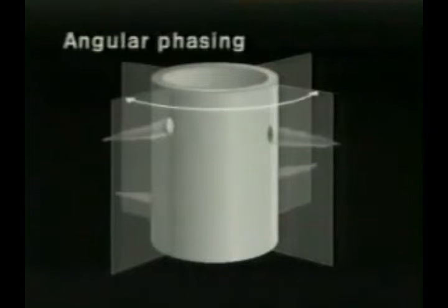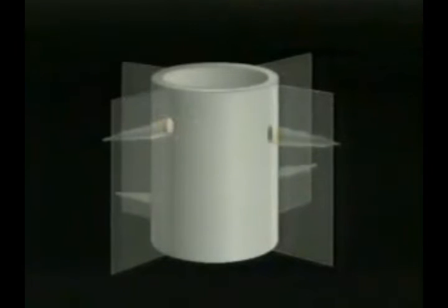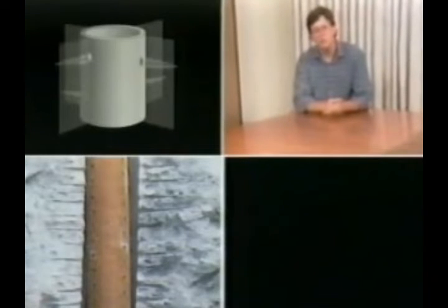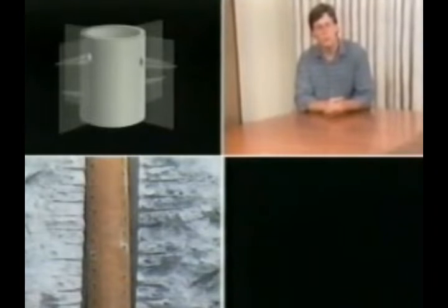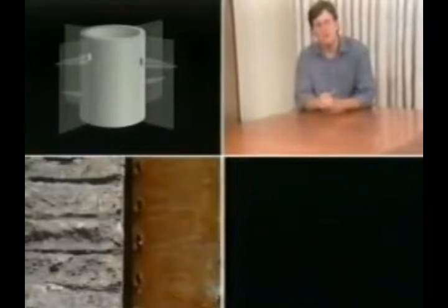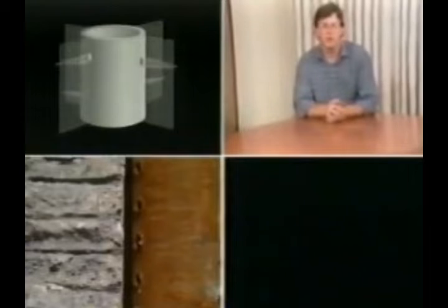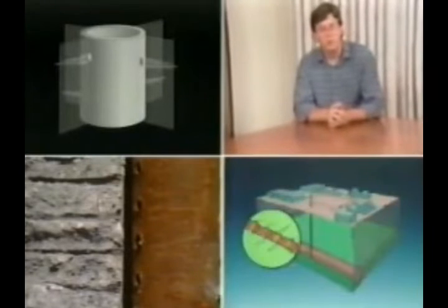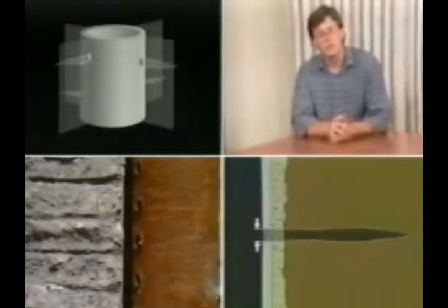Penetration, shot density, phasing, and hole diameter are the variables that may be adjusted depending on the particular perforating situation. Generally speaking, a technique that ensures the maximum number of open perforations extending beyond any damage is the best alternative for a natural completion. When fracturing or gravel packing is to be undertaken, perforation diameter becomes important. In the next unit, we shall follow a perforating job as it is performed. For now, please read sections 1 and 2 in your manual and work the appropriate exercises.